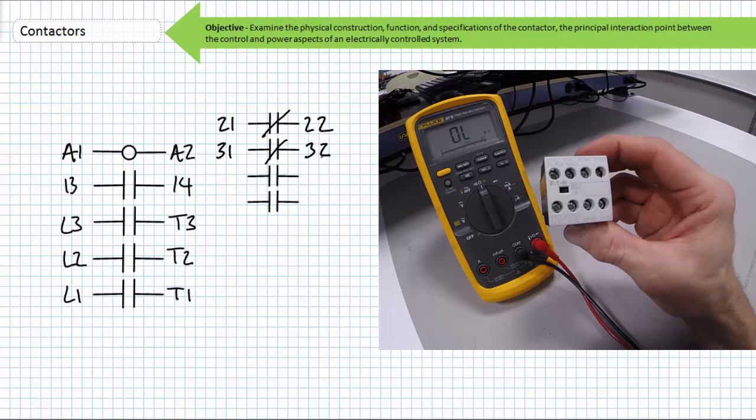This is the third set of auxiliary contacts associated with this contactor, so the first digit of these terminals is given the number 3. Since it is a normally closed switch, it is assigned 1, 2 for the second digit, for terminals of 3-1 to 3-2.